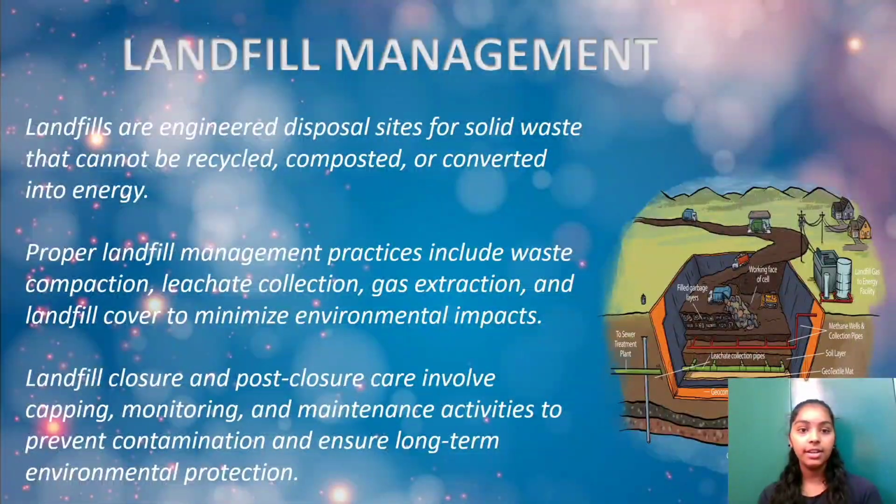Landfill management. Landfills are engineered disposal sites for solid waste that cannot be recycled, composted, or converted into energy. Proper landfill management practices include waste compaction, leachate collection, gas extraction, and landfill cover to minimize environmental impacts. Landfill closure and post-closure care involve capping, monitoring, and maintenance activities to prevent contamination and ensure long-term environmental protection.